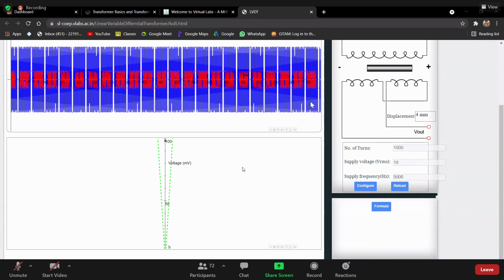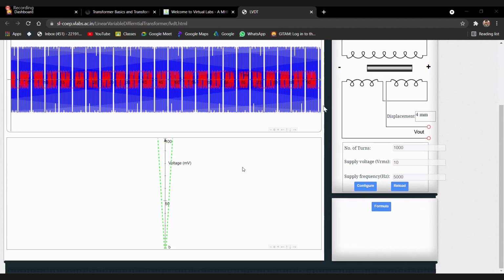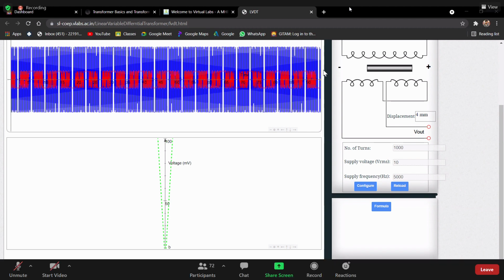Explain about LVDT. LVDT consists of two coils. One is primary and the other is secondary. In the secondary we have another two, positive and negative, and we have an armature which decides whether we are having a positive voltage or a negative voltage, sir. It helps to get positive voltage output or negative voltage output, based on the movement. Oh, yes, right. Wait one second. Stop sharing.